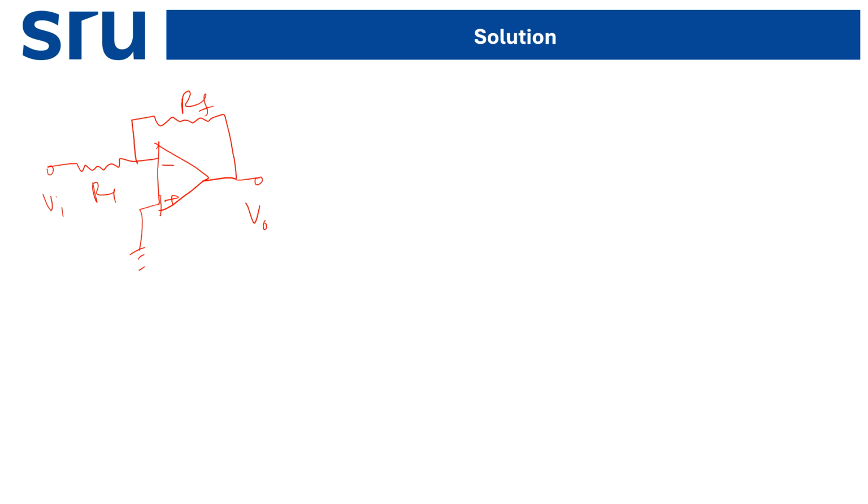For this case the input and output should have been a similar waveform, the only change being in the amplitude and also the phase. This is our expectation, but the customer complained that they are not getting this. If we give a square wave, we are getting a triangular wave.